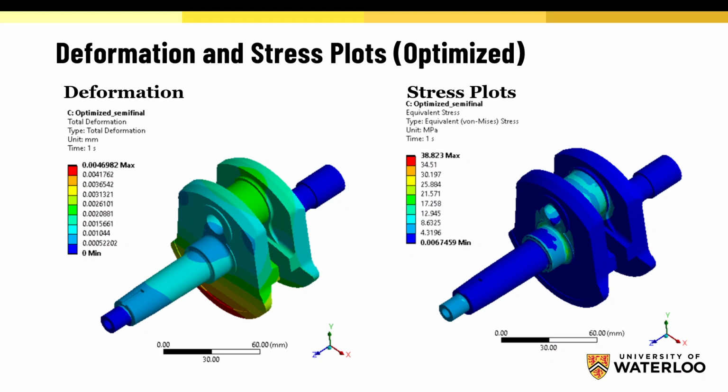Okay, so the first thing is looking at the amount of energy that's moving in and out of the system. Say you get a non-sensible temperature, like you're expecting a temperature to be 200 degrees Celsius and you get 2000: where is the heat generation coming from? Where is that extra energy coming from? So first thing would be to understand the order of magnitude, and then from there, okay, in the thermal analysis procedure, are the heat sources and the heat sinks in the right spot? Do they have the right magnitude? Is the flux correct? All of those things.